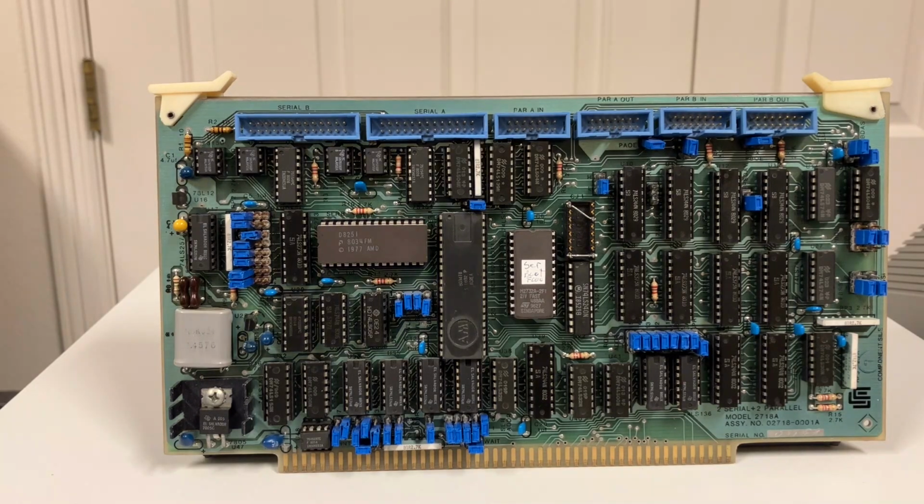And at F800, I have myself a monitor, and then at FD00, I have the turnkey monitor. At FE00, I have the multi-boot loader, and at FF00, I have Altair's disk boot loader. Those are all the standard addresses for those.